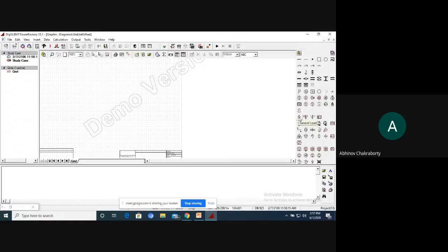This is your load side, again, general load. You have your MV load, you have your LV load, that is the medium voltage load, low voltage load. Right, you have your transformers over here, you have your 3 winding transformers over here. And apart from that, you have your capacitor, as I already told you, for the APFC panels, automatic power factor control. You have the capacitors over here. So almost everything that you need for designing a system is over here.